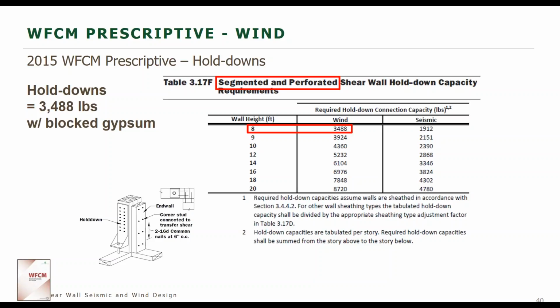Absolutely. Okay. And I'm not aware of any seismic provisions. Michelle might be more up on those. Yeah, I can't remember what the seismic triggers are, but probably above Seismic Design Category C, so maybe A, B, and C or something like that would be where you'd be able to use the IRC braced wall provisions, but check the IRC to see where that happens.